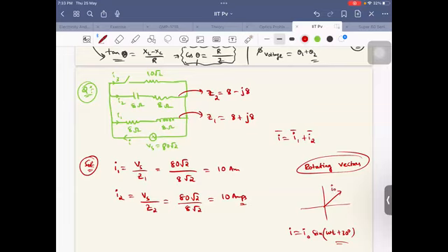I naught is the length of the vector, and the 30 degrees is called the initial phase. This vector rotates with angular frequency omega. So phasors are one kind of vectors, and you know vectors cannot be added simply. If these two are vectors, can I write 10 plus 10 as simply 20? No, right? Because these are not scalars. Just the same way, I1 and I2 are not scalars, so you cannot simply add them.